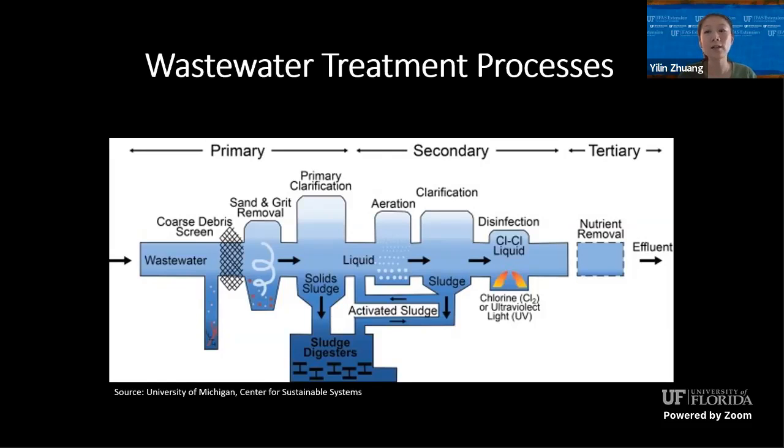Settling tanks are designed with mechanisms to remove both the settled solids as well as the floating solids. Primary treatment generates a primary sludge. The sludge is removed and pumped to a solids treatment process for ultimate removal. The wastewater still has solids remaining after primary treatment.